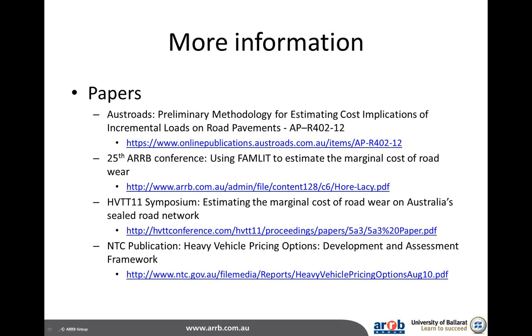Okay, back again. The change in pavement strength was plus or minus 30% from the original strength. And we took that 30% both from the pavement and the subgrade. I had it written down, I just forgot to mention it, or I wasn't reading my notes when I went through the slide. Where's the next question?